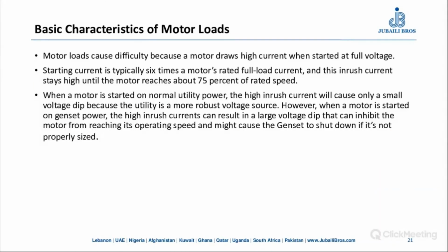So the last topic of today's webinar is the different types of starting methods that can be used for motor loads. First, let's have a look at the basic characteristics of motor loads. Motor loads cause difficulty because a motor draws high current when started at full voltage.